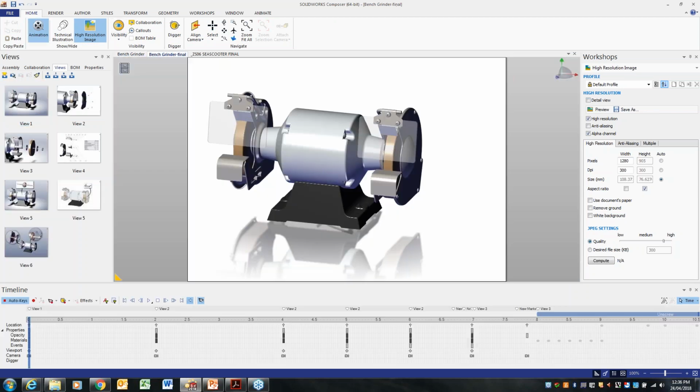with the constraint of time, I'm just going to show you something that we have created. All I have to do is look at any of these particular components, and I have the option here on the timeline. So when you open animation, you get the timeline created here, where you have the properties, the camera viewport and the location. These are the three main features that you need to set for any component as you move along the timeline, and adjust that to a particular time, and it will reference that to the previous to create an animation.